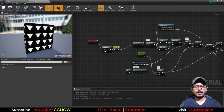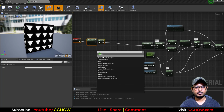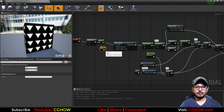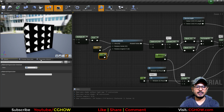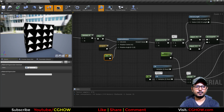Okay, and if you want to randomize the rotation of these, you can take the custom rotator, connect it here, and the center will be 0.5, and this is your angle. And if you change it, all triangles will rotate on the same axis. Let me make it 0.5 on the same axis, see, 0.2, 0.5.